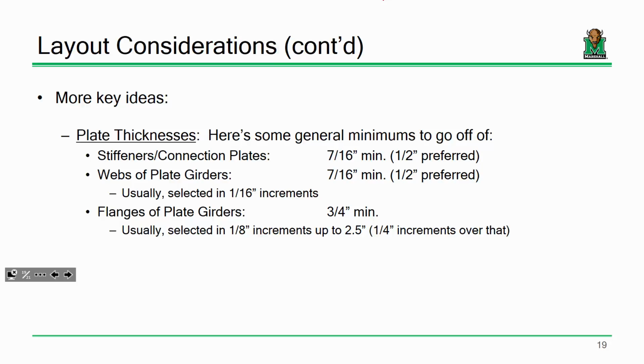You start seeing stuff lower than that, and you start getting issues with slender flanges and local buckling, and it becomes undesirable. Plus, a lot of this stuff has to do with handling. If you try and fabricate a girder with like a 1/4 inch web, you might have all the capacity you need, but your fabricator is going to be yelling at you because if you ever handle structural plate by itself, it's got all the stiffness of a piece of wet spaghetti.